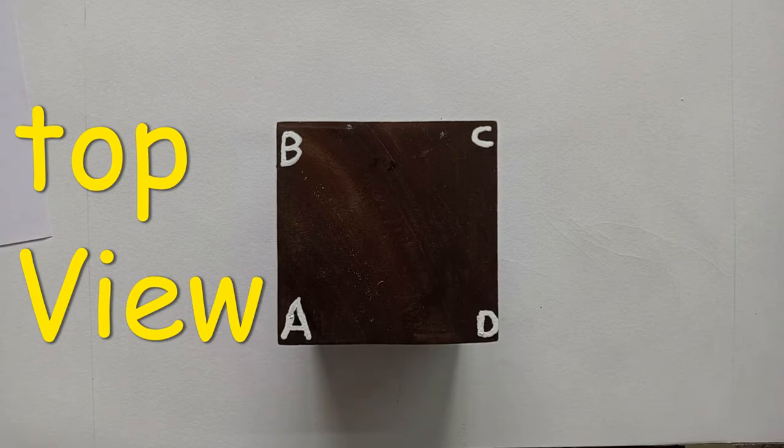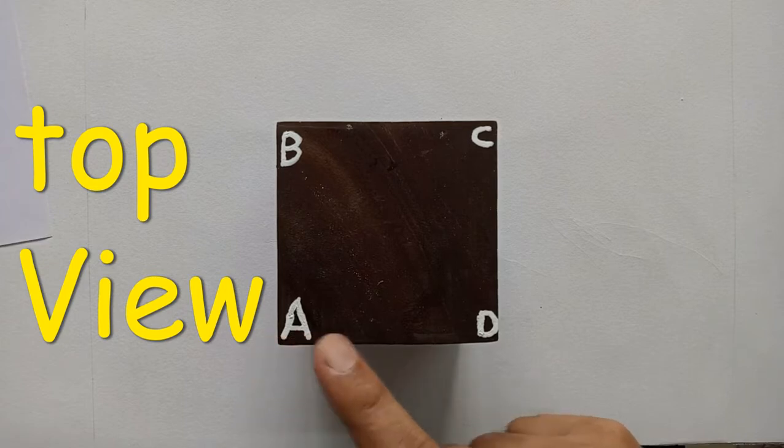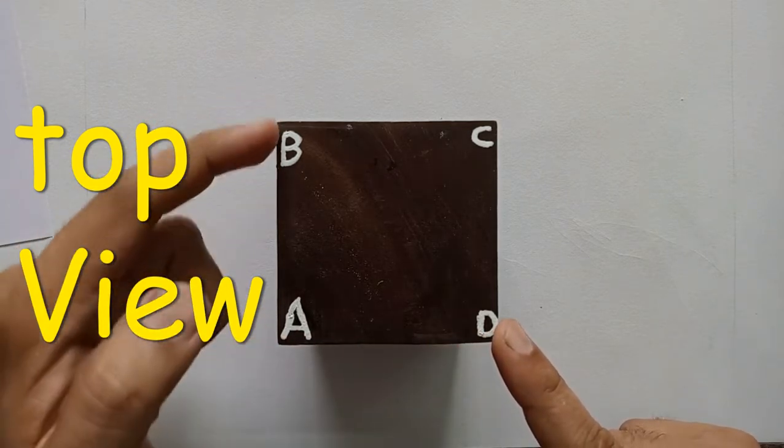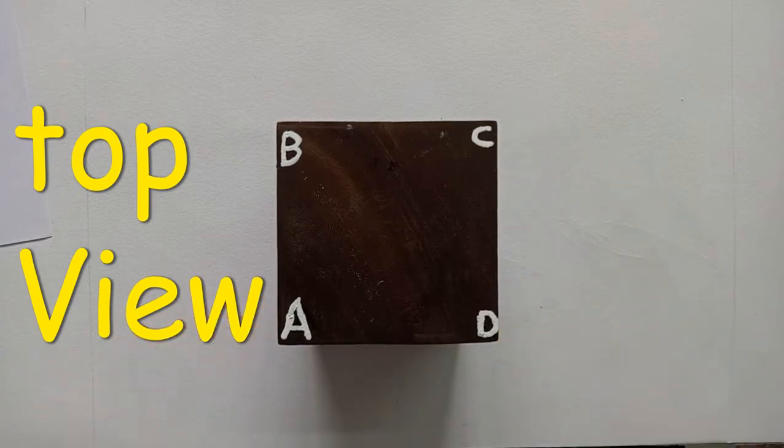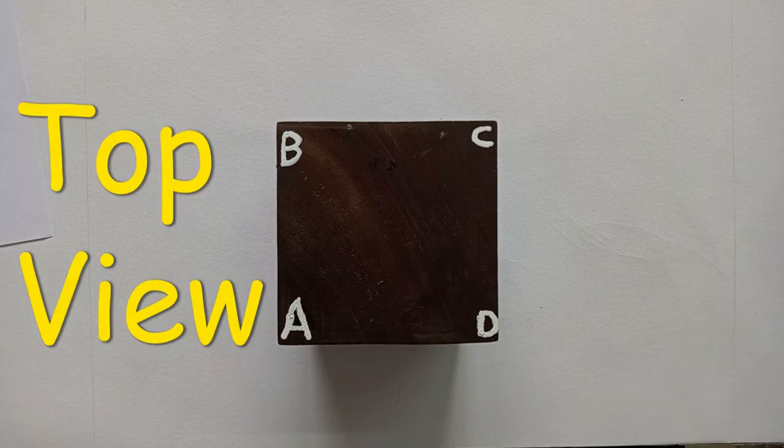The edge length of the cube is given as 50 mm. So what is 50 mm? The length of AD, or the length of AB, or the length of BC, or this length, it is 50 mm. So when you are observing from the top, you are getting this as a square which is having a length of 50 mm. That is our top view.